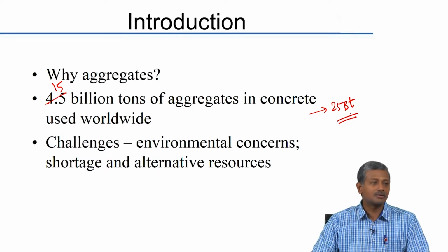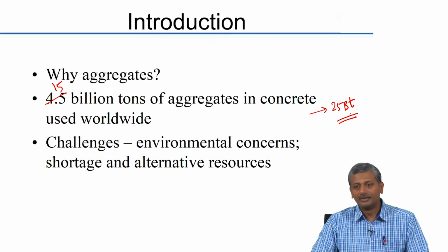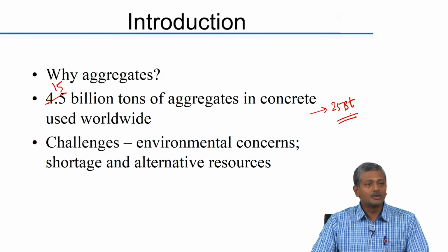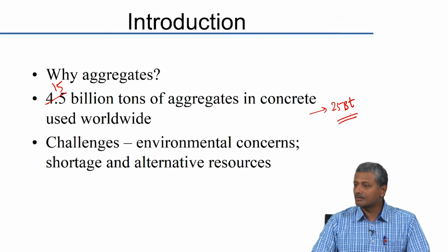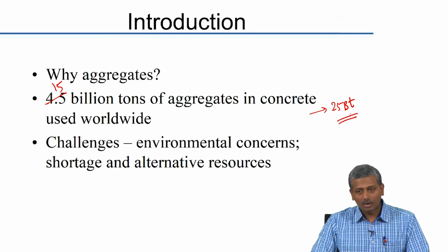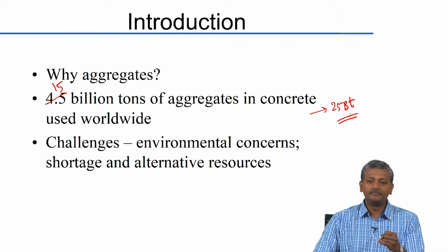Cement is the most costly or expensive ingredient in concrete, because of which if you use more cement, your concrete is going to be more expensive. So the idea is to pack as much of the concrete volume as possible with aggregate and use only as much cement paste as required to obtain what characteristics? Bonding. What else is cement paste providing in the concrete? Workability. Right?